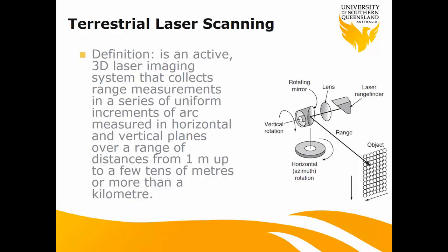We rotate the instrument around the vertical and horizontal axes, so we can simultaneously get thousands of returned laser points, collecting a huge amount of high-density, high-accuracy three-dimensional points.